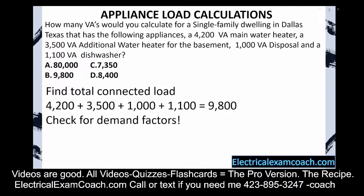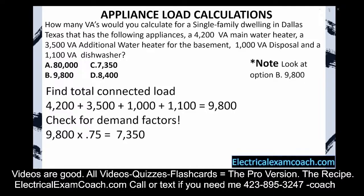Sure enough, we have four or more fixed appliances, so we can apply the 75% rule. We take 9,800 multiplied by 0.75. That gives us a new reduced load of 7,350 VAs. I want to note that if you look at option B, it was 9,800, as if you didn't apply the 75% rule. You got to be careful. Oftentimes, they'll have one of the answers be as if you missed or added one of the steps that you shouldn't have.